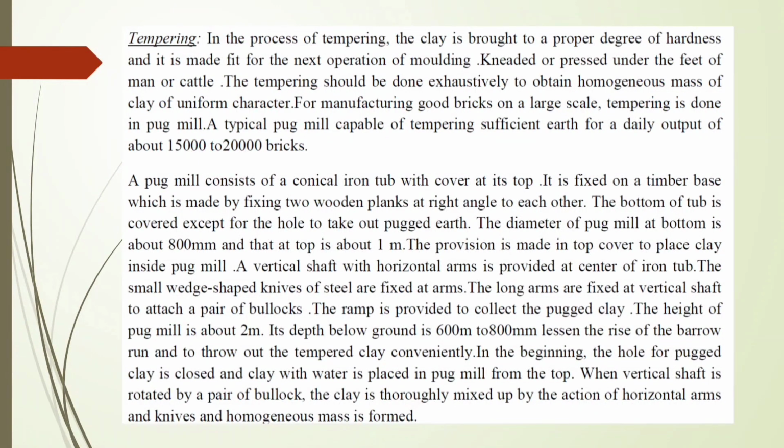Tempering. In the process of tempering, the clay is brought to a proper degree of hardness and it is made fit for the next operation of molding. It is kneaded or pressed under the feet of man or cattle. The tempering should be done thoroughly to obtain a homogeneous mass of clay of uniform character.